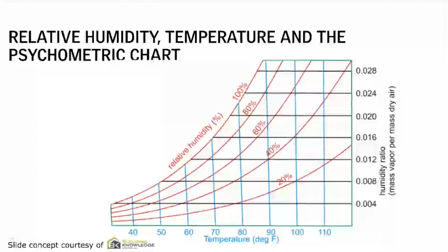And condensation can be a challenge for skylights, particularly if they are low performing skylights or it's in a very high humidity application. Skylights by nature being sloped are more susceptible to condensation than vertical windows. So we've got to keep that in mind. There's a couple of strategies to reduce that risk of condensation.